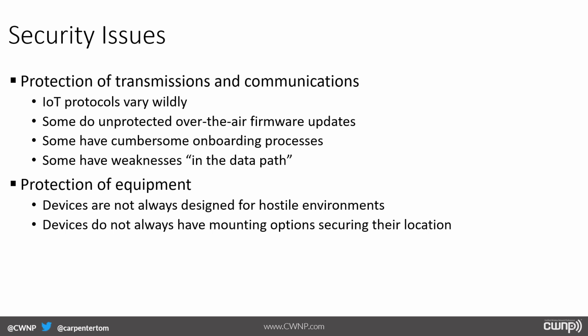Early on, think about it, it's wireless, right? So a wireless sensor is not as scary to us as a wireless actuator, because an actuator does something and a sensor just tells us something. So if we've got wireless sensors, that's not as scary because they're just reporting back to us what's going on. If we've got an actuator, the scary part is, well, if someone hacks into that and they can shut down the machine, or they can speed up the machine, or they can take other actions, then it could cause harm to people around it. It could reduce production time cycles, or increase production time cycles, and so forth. So there were concerns early on, obviously, but as we got security, it wasn't as big of a concern.